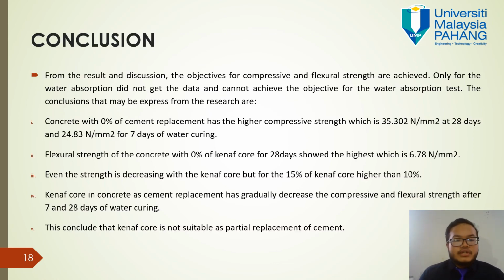So for the conclusion, from the result and discussion, the objectives for compressive and flexural strength are achieved. Only the water absorption did not get the data. So the conclusions that may be expressed from the research are that concrete with 0% of cement replacement has the highest compressive strength, which is 35.30 Newton per millimeter squared at 28 days and 24.83 Newton per millimeter squared for 7 days of water curing.